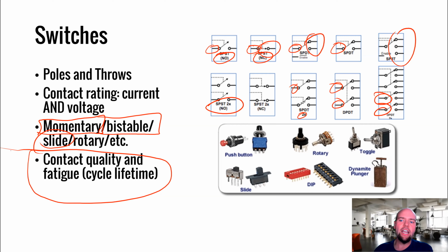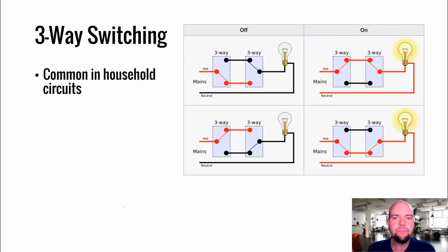You'll notice in old-timey movies where somebody has this big giant lever and they switch it and there's sparks that fly when they do the switch. That's a real thing. There's actual switches that are switching very high voltages, very large currents, where it needs to be a big physical switch. Then they'll actually put the physical switch inside of a box because the sparks that fly off of that thing and the plasma that arcs when you do the switching is so violent and so dangerous. So that's a real thing. So voltage matters with switches, as does current rating.